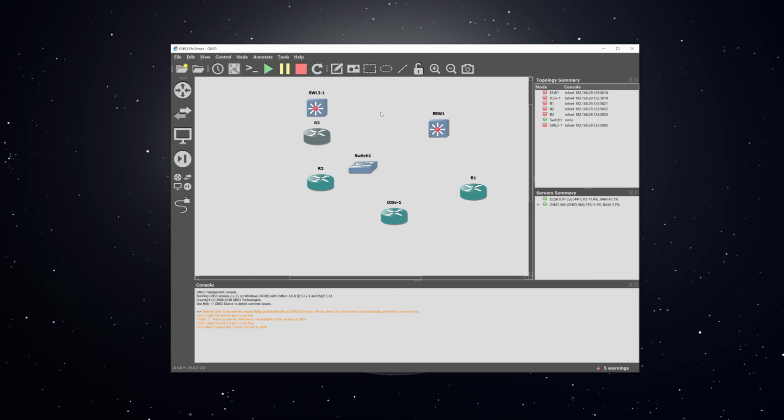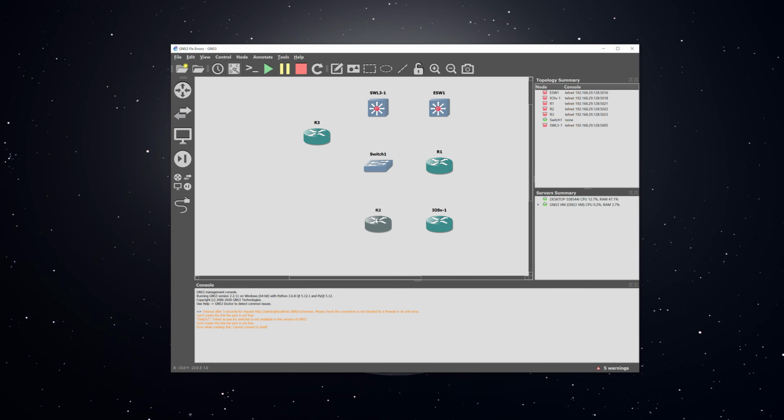All right, and then one thing that I always do in order to make everything look nice and clean is I always have snap to grid on. You can click the one beneath it that shows grid, and then it looks like that. I prefer just to have snap to grid on. Then you can make sure that everything will line up. And then I'm going to use the connector tool to connect all the devices to the layer 2 switch in the middle.